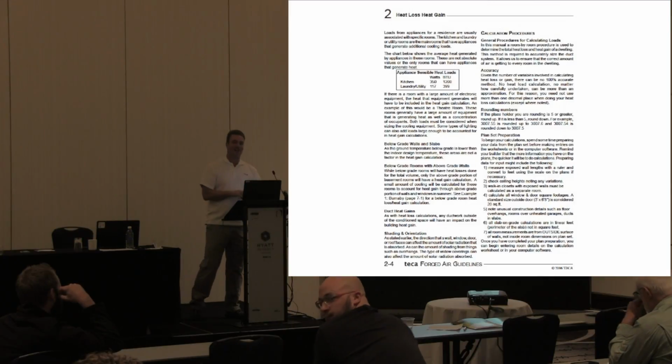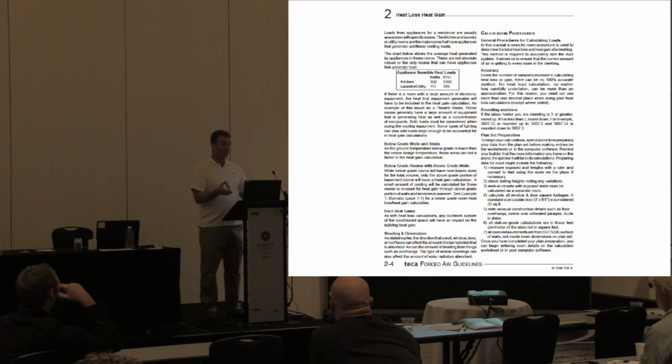But when you're doing the cooling side and you have that big theater room and everything else like that, this is one of those situations where you're going to want to make sure, is that the only room you're going to need it in? If it is, then maybe you want to put a separate system in that room, like a ductless or whatever for those guys that have done that kind of stuff, to control just that room.